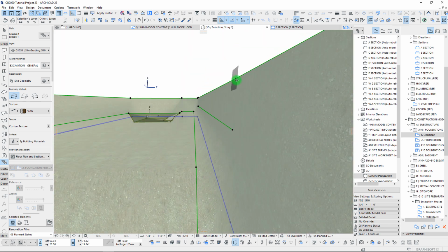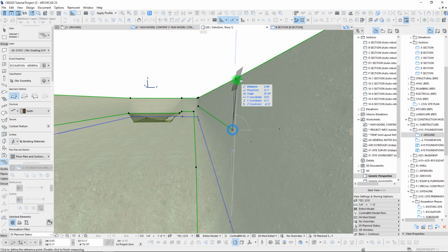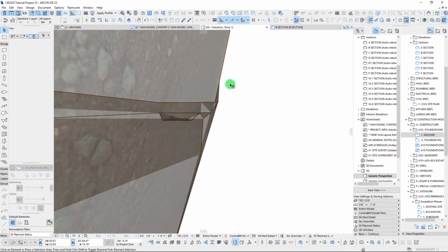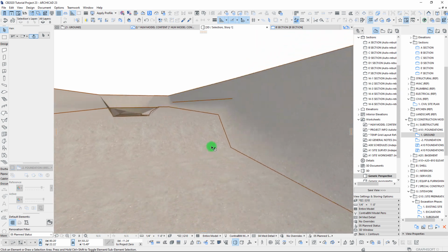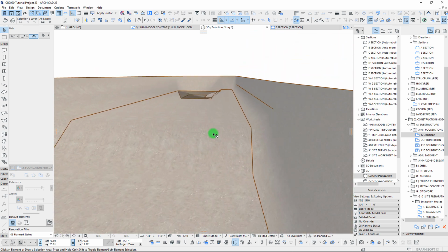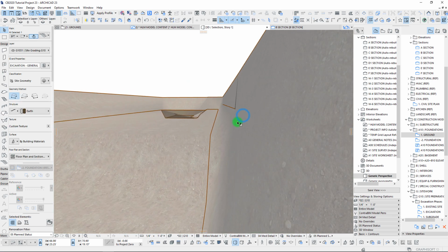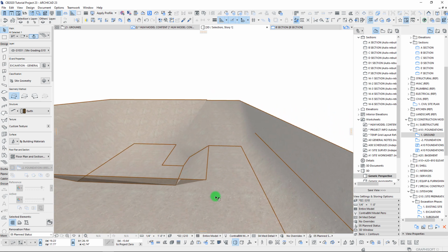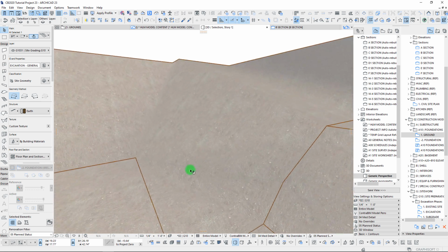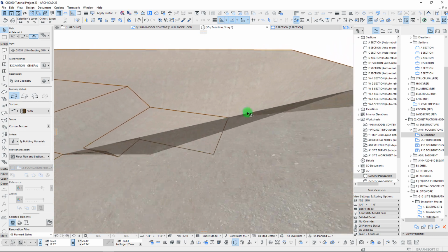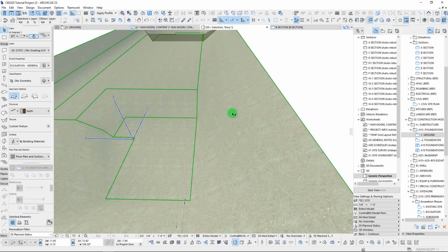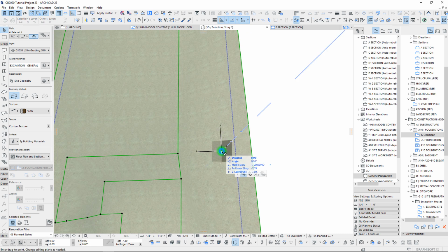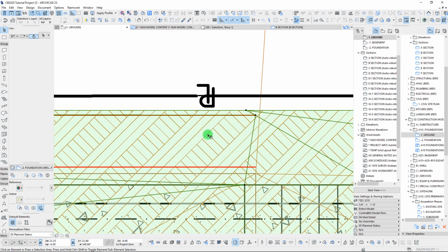If the soil will allow you to do a straight cut, in this case, we're only going down a little over 2 feet. So that's probably allowable. It's just when we get to here where we need to go down much further, where we may need to work in some shoring. So this would actually probably take care of us on that side. Over here, we have kind of a nice clean ramp for getting down. This is probably acceptable to leave as is. I like that slope. Once again here, we could probably use just a little bit of help by creating another kind of shelf over here.